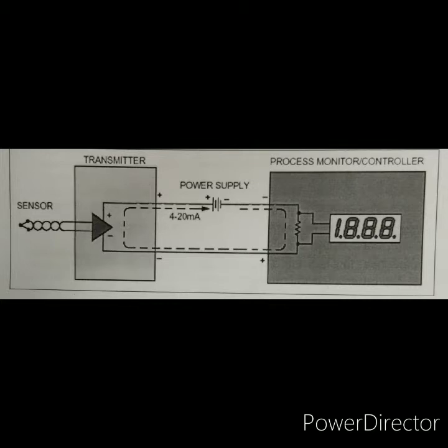Sensor transmitters are primarily used to produce an output with a higher transmission range than the sensor itself can provide. For example, a sensor which outputs a small voltage or resistance value has a short range due to losses inherent in transmission wires. Range is the difference between the low and high values to be measured. This is always dependent on the physical sensor's range or calibrated range. Span is the difference between the range values.